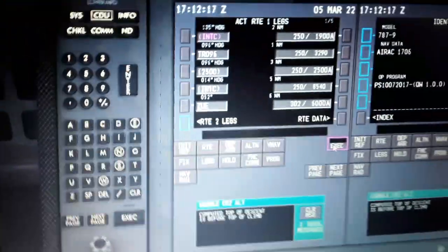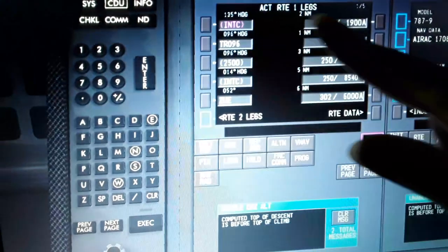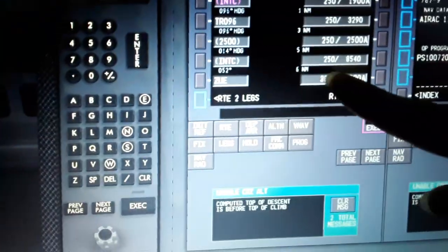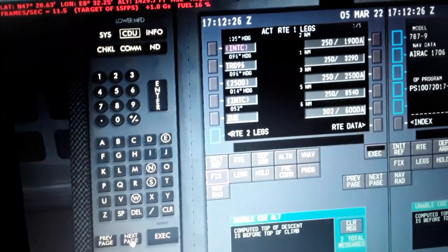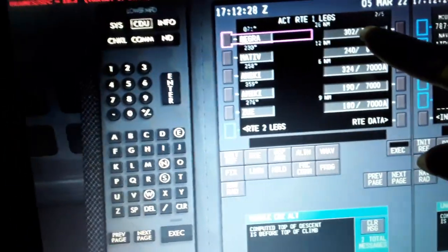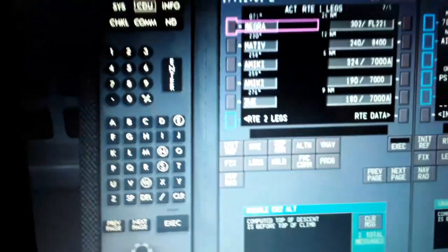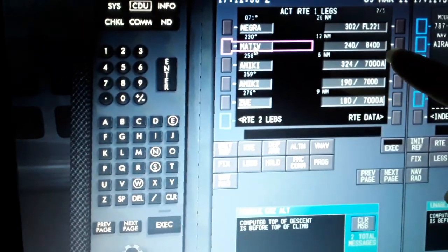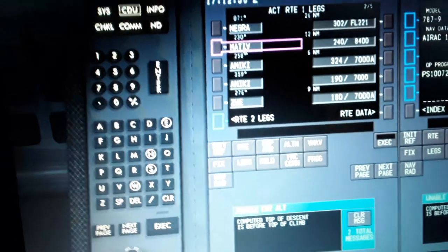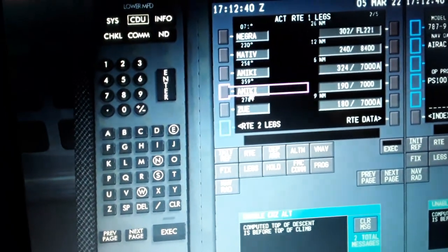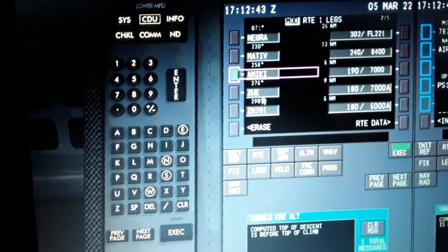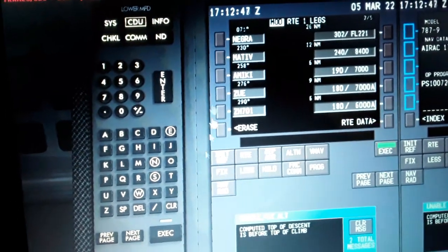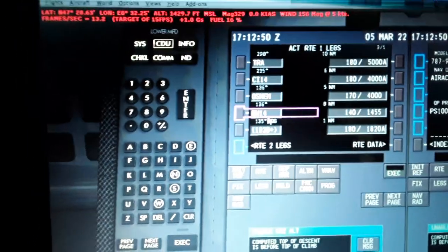So we have an active route from takeoff, first waypoint, the airspeed and the altitude, then Zui 6 nautical miles, 302 knots, 6,000 above the sea level, then Negria 26 nautical miles from Zui, 302 knots, flight level 22,200, then make a right turn, heading 230, 12 nautical miles from Negria, descent approach over here, Amiki, Zui, Zurich 701, approach and landing over here, and also runway 14.